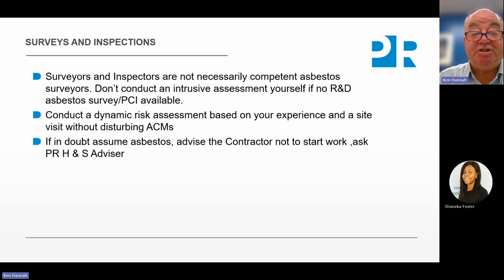Your dynamic risk assessment is based on your own experience and a site visit without disturbing ACMs, and based also on the history of the building. Now, if you don't know, you must suspect that there is asbestos present. So if in doubt, assume asbestos, advise the contractor not to start work or to stop work, and ask a health and safety advisor.